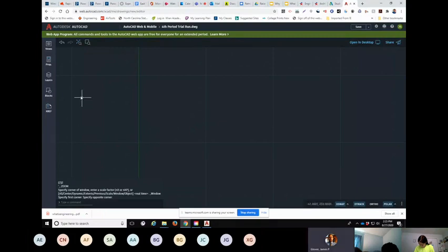Now, we're really far in, so let's just zoom to extents. If you've got a mouse attached to your computer with a scroll wheel, you scroll it backwards and forward, and it can zoom in and out for you without having to go up here and mess with the zoom level.